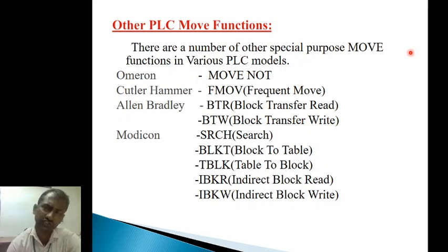In addition to these functions, some other functions are there. Those are a number of other special functions. For the Omron software we have the move not function, for Cutler Hammer we have the fmove function, for Allen Bradley there are block transfer read and block transfer write, and for the Modicon PLC there is SRCH, that means search, block to table BLKT, table to block TBLK, indirect block read IBKR, and IBKW, indirect block write, like that. So many other PLCs also have other move functions.